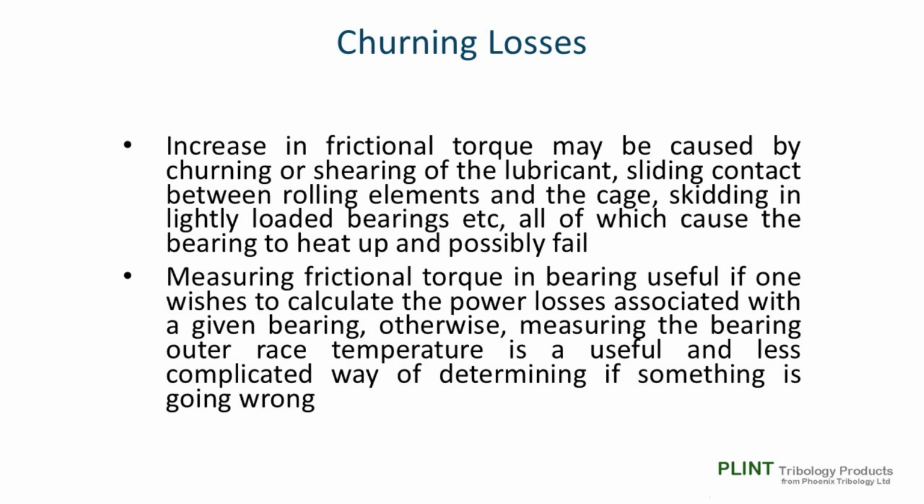Frictional torque in a correctly lubricated rolling element bearing starts more or less at 0, then increases with increasing speed of rotation. Rolling element bearings are, by definition, very low friction devices, and measurement of frictional torque is not of very general interest.